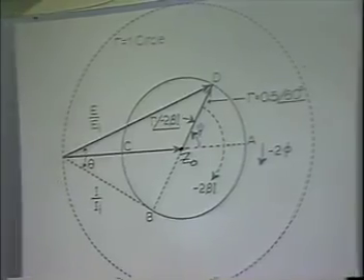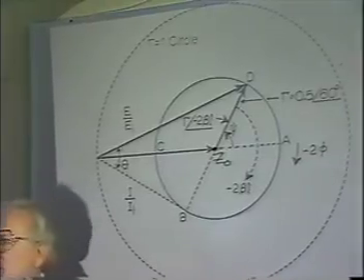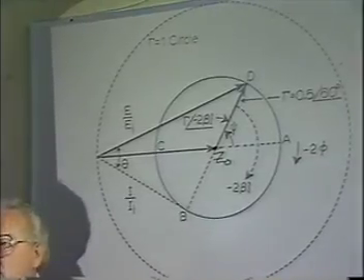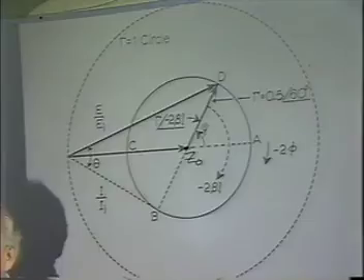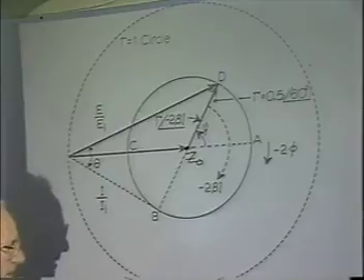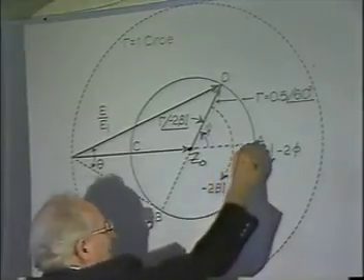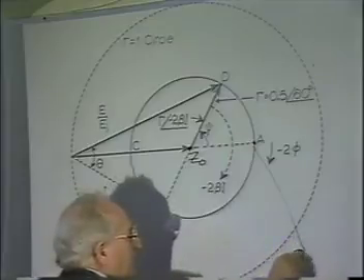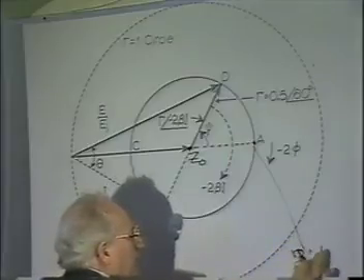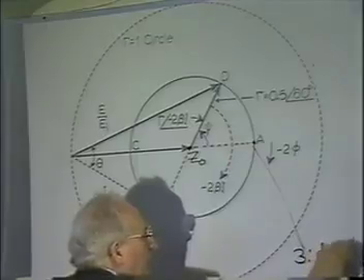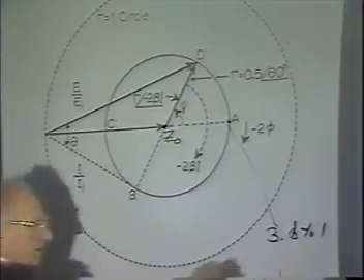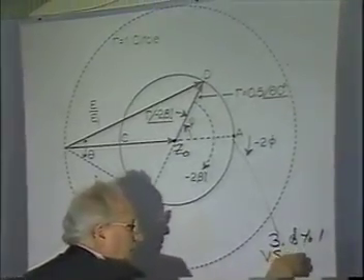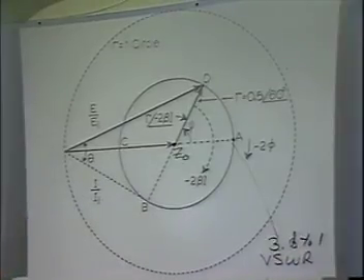What do you find for the voltage standing wave ratio of this 0.5? Same one I've told you to remember automatically all of the rest of your time in RF and microwave work. What's the voltage standing wave ratio? 3 to 1. What's the return loss? Okay. So this point here, as you said, is 3 to 1. 3.0 to 1. Voltage standing wave ratio. It's very important because we'll come back to that value a little later.